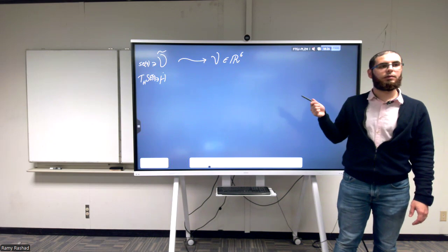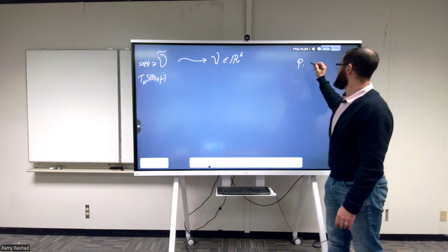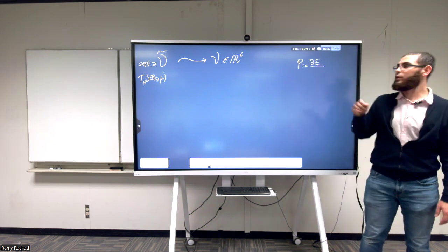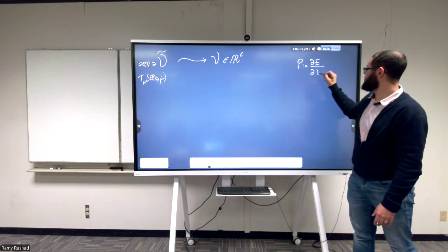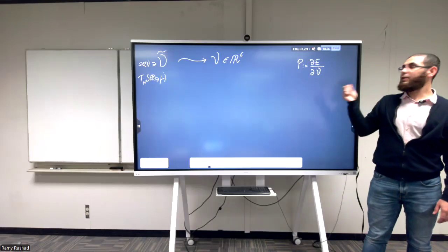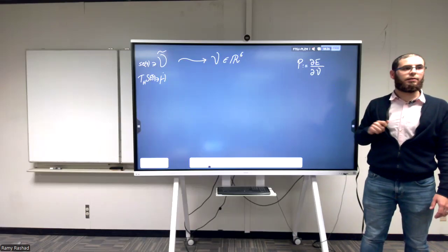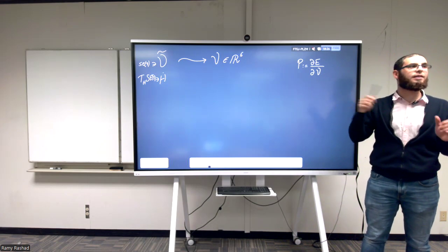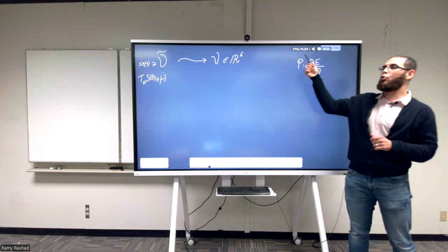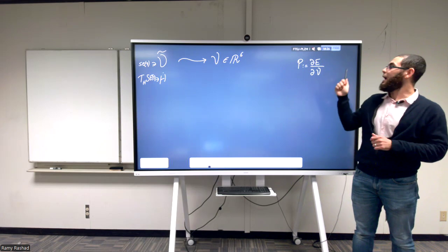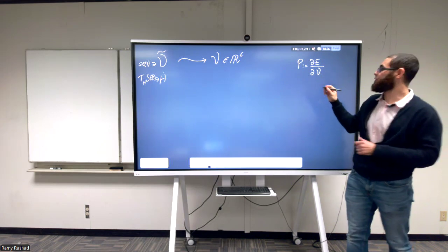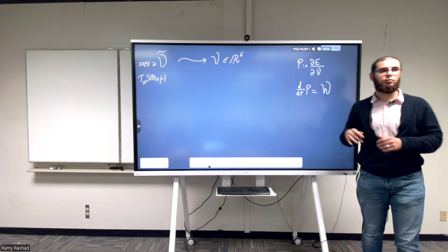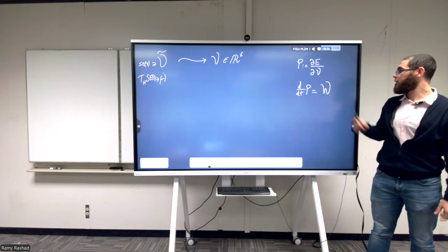What about the momentum? The momentum came from the definition that we took the gradient of the kinetic energy and we divided by the twist. The gradient is not a vector. That's the bomb. The gradient is not a vector. The gradient is a covector. And that's why momentum is also a covector. And that's why the rate of change of momentum, which is equal to the applied forces, the generalized forces, torques and forces together, is also a covector.